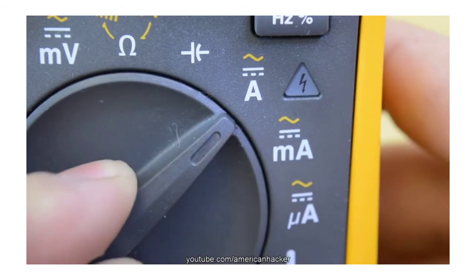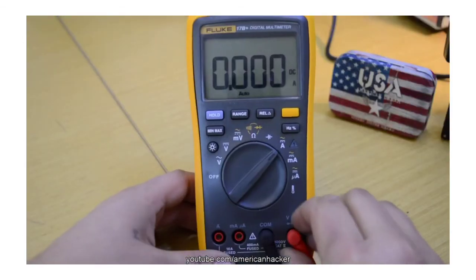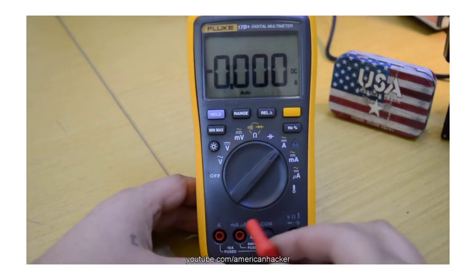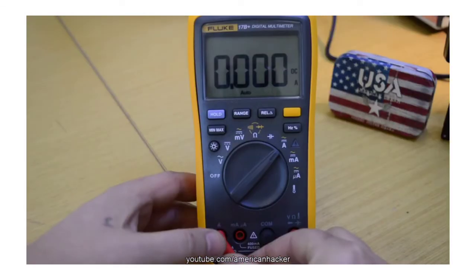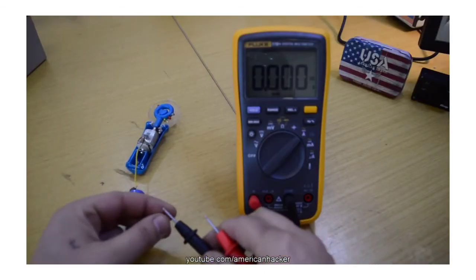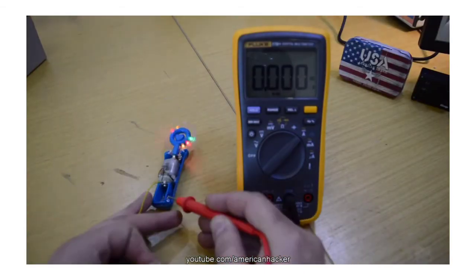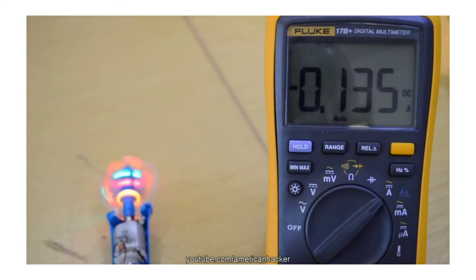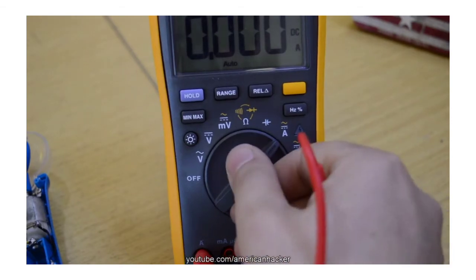The final setting is to set the dial to measure current, and for almost all multimeters there is a separate jack for measuring current. This multimeter has 2 amp jacks, one for currents up to 10 amps and one for currents up to 400 milliamps. I always place the jack to amps. If I need more accuracy, I switch the jack to milliamps.